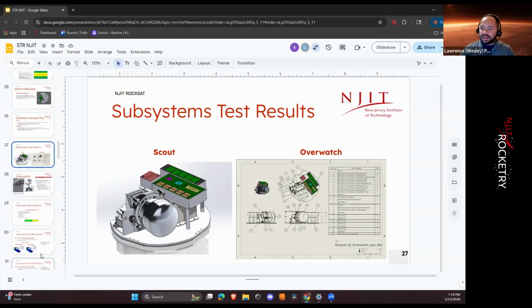Alrighty. Next thing is, are you planning to charge at Wallops Flight Facility? So I believe we're not charging at Wallops at all. The batteries we picked, they don't have a very large self-discharge rate, and we plan on mechanically isolating the connectors, and hopefully when it releases, it can close that circuit loop. So we don't feel that that's going to be a big issue over the span of the month that it's going to stay on the rocket.